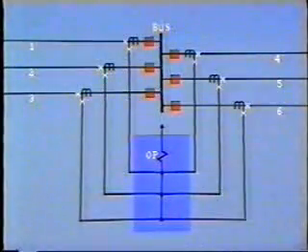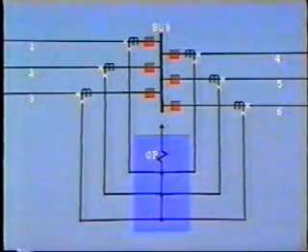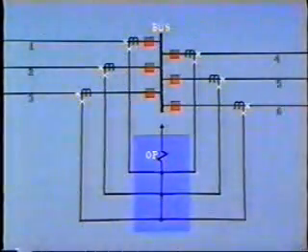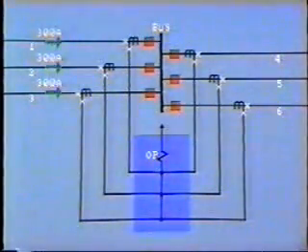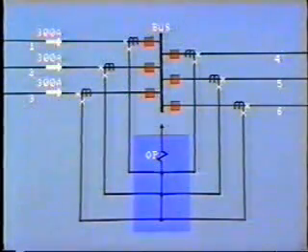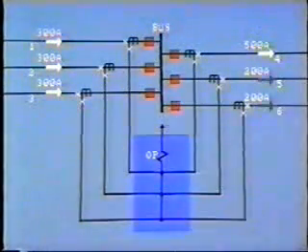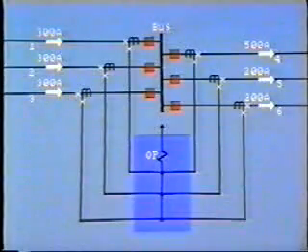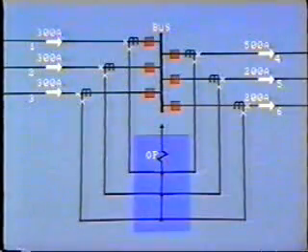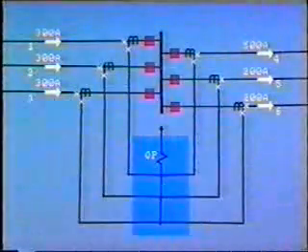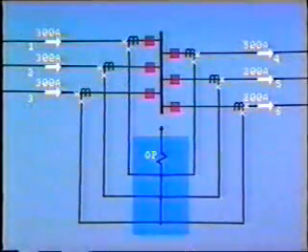Let's look once again at an example of simple current differential. There are 6 circuits connected to this bus with 300 amps entering on each of these lines 1, 2 and 3. 500 amps flows out on line 4 and 200 amps out on line 5 and line 6. There will normally be a set of CTs and a differential relay for each individual phase. For good performance, all of the CTs must be of identical manufacture and the same ratio. For simplicity, we'll look at just one phase on each line.